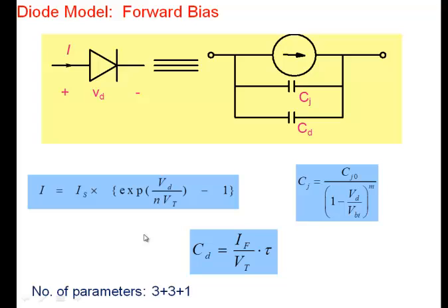You have the model, right? You have the equations. To use the diode, what will you ask me? Give me the value of IS. So all diodes will have this particular model. What will differ from one diode to the other is the parameters. So you will ask, give me the value of IS, give me the value of N, and maybe give me temperature. Then if you give me all of that, I now know and can calculate the current.